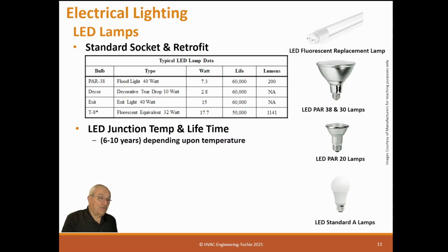So most of the time, switching from incandescent is fairly easy, because you can get a bulb with about the same lumens output, much less wattage into the fixture. But if you're doing a fluorescent change-out, it's normally better to change the fixture, because instead of those 2x4 fixtures, you probably only need 2x2 fixtures with LEDs, because there's about 37% more light in an LED than most fluorescent bulbs. So that's why, when we're doing a lighting retrofit, we go back to a lighting design. In the old days, when we did fluorescent to fluorescent, we didn't need it. We could just replace them with a bulb of the same lumen output, and we were good to go.